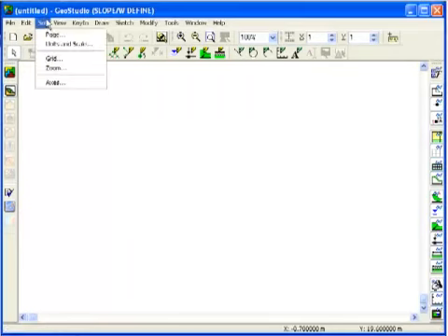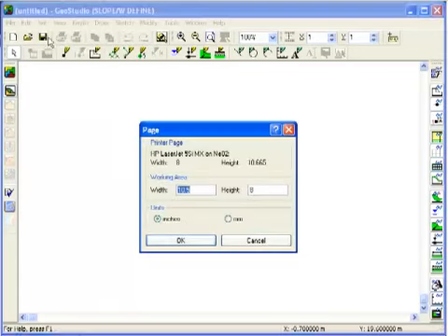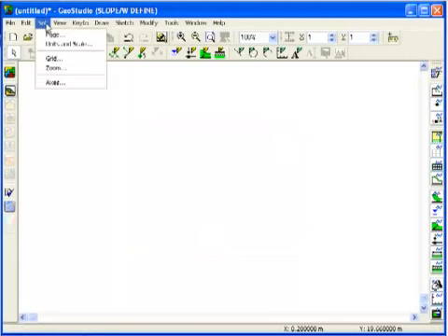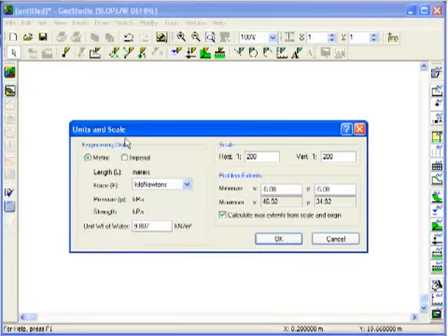When developing a model, the first step is usually to set the working area, which defines the size of the space available for defining the problem. The working area may be smaller, equal to, or greater than the printer page. The next step is to set the scale. The scale should be set such that the minimum and maximum extents in SLOPE match those required for the analysis. You can define either the x and y extents or adjust the actual scale of the problem.